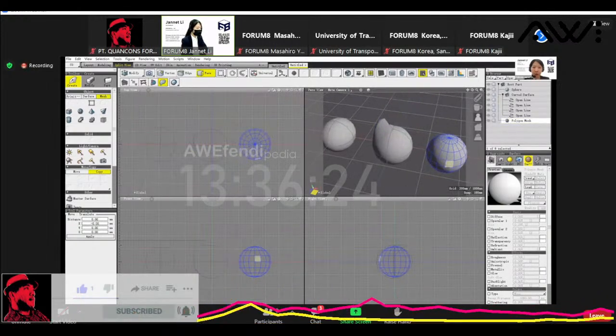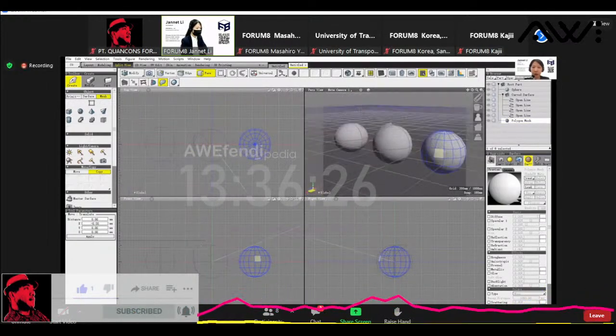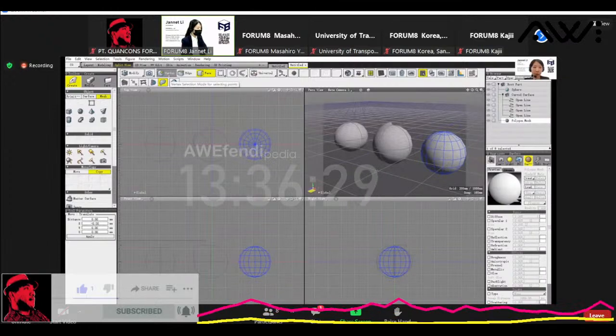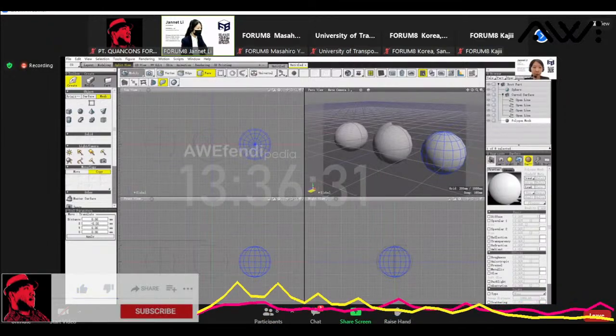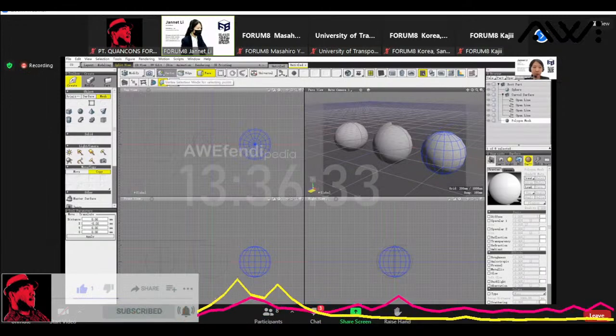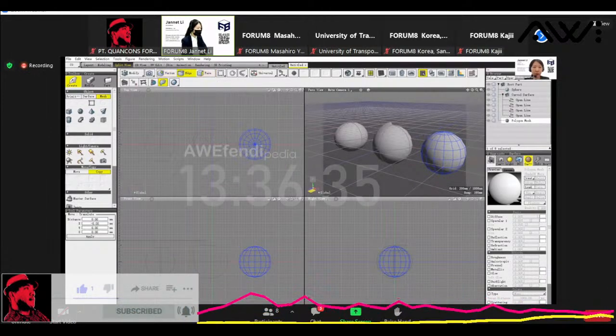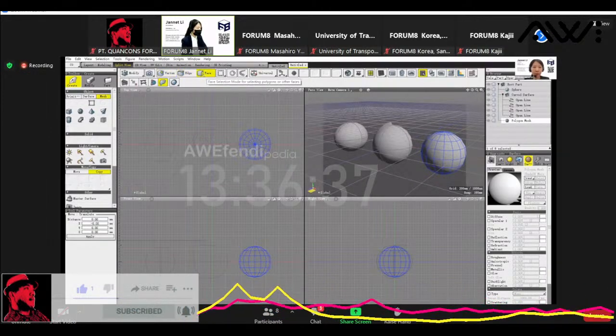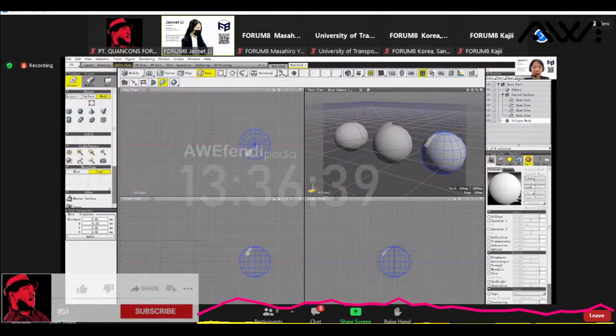And if you go into the third mesh sphere, please choose that one in the browser and then go into modify again. And then this time, instead of vertex, we're going to choose face.